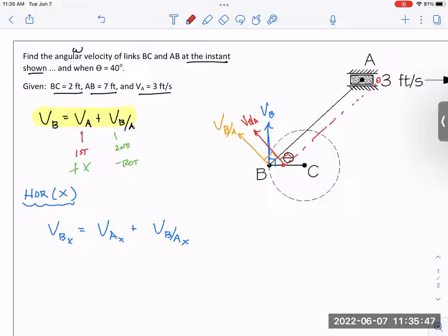90 degrees, isn't velocity always perpendicular? Now it's rotating angularly, if you will. But that's how it gets back into position right here. Does that make sense? You see why I drew that orange velocity of B relative to A 90 degrees to that? It's rotating around that red crank arm. We got more than one problem to do, and so you'll have time to see if you can get your mind around it. But that's the two things I got to draw in here.